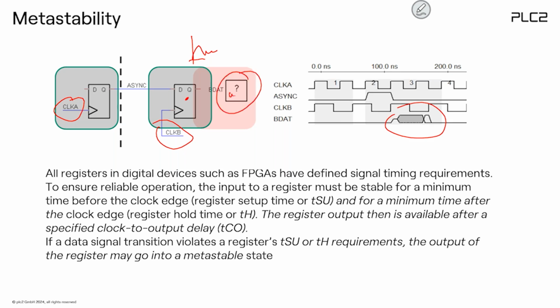So now you have to take care of the following component which is connected. This flip-flop usually always has a name: it's called the sync flip-flop. The point is, this ringing, this metastability, happens whenever you violate the setup time and the hold time.